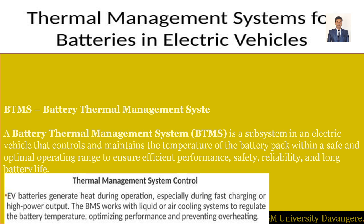All right. Let us say the battery. What should be the battery temperature then? You can ask, sir, what is the temperature of the battery that we have to maintain? You can maintain from 15 degrees to 35 degrees centigrade always for the batteries. All right. So you can go for this nominal temperature. Beyond that, it should not go, and below that temperature, it should not happen. We should not increase the temperature to more than 45 to 50 degrees centigrade. Also, you can go to a negative temperature also. So that will be a very critical factor for the BTMS.